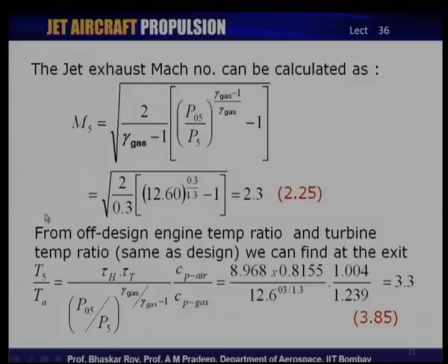What we can do now is find the off design engine temperature ratio and the turbine temperature ratio. The turbine temperature ratio holds the same as the design, because it is still working under choking condition, and hence its temperature ratio and pressure ratio would hold.